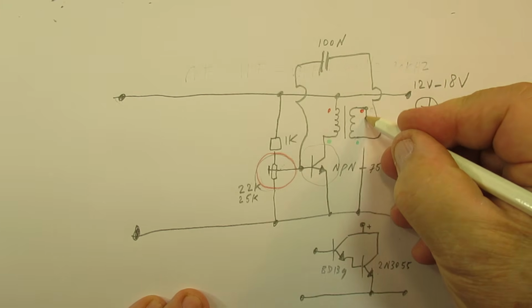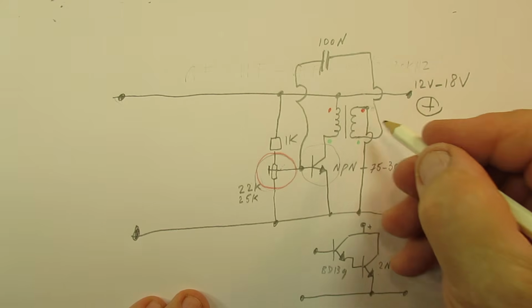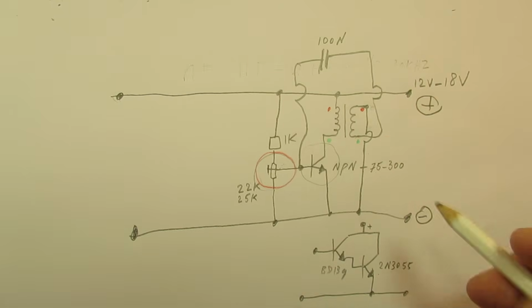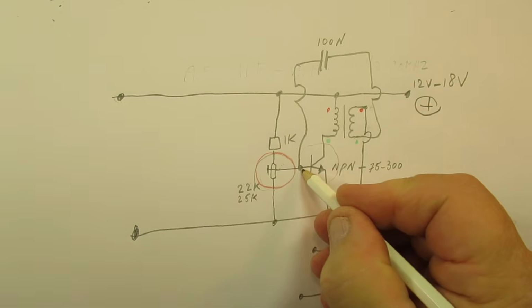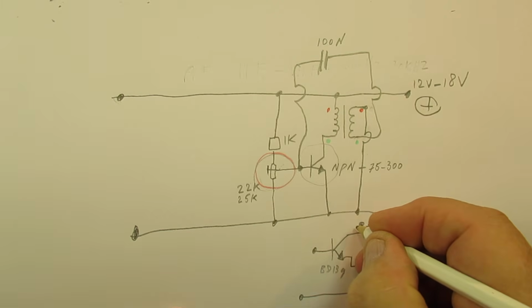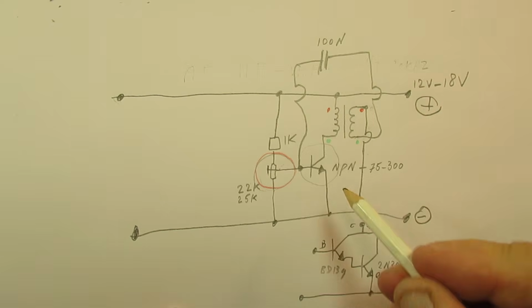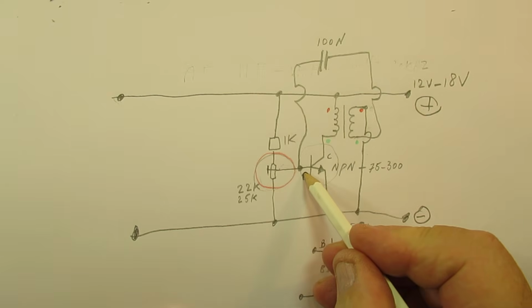And connect this one here. Of course, they must not meet, these two wires. That will be a shortcut of the transformer. Connect the other part to the minus. So that is your first, say, experimental thing to do when you want to get such a circuit into oscillation. Use this 1 NPN transistor. Use a Darlington. Can use a Darlington. So I want to indicate here collector, base, emitter, and here also collector, base, emitter.